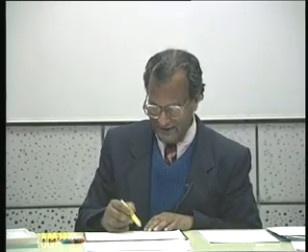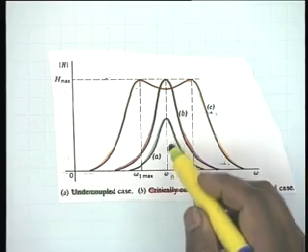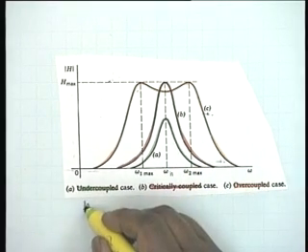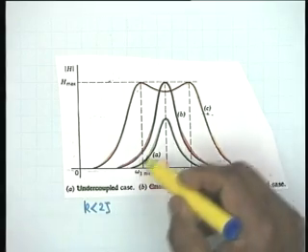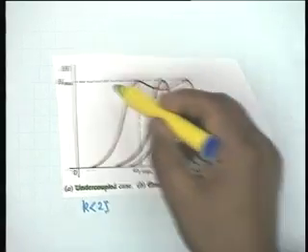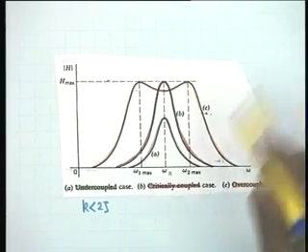Okay, the green here is the undercoupled case. Undercoupled means K less than 2 zeta. It reaches a maximum, but this maximum is not quite H max, which can be achieved.